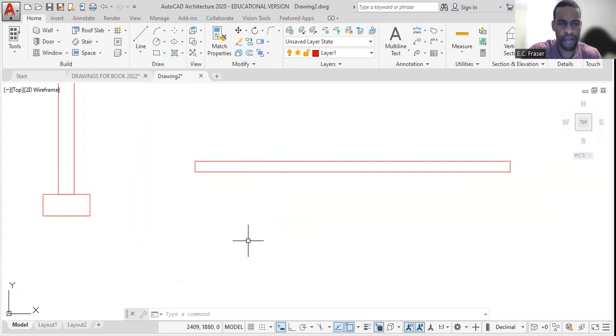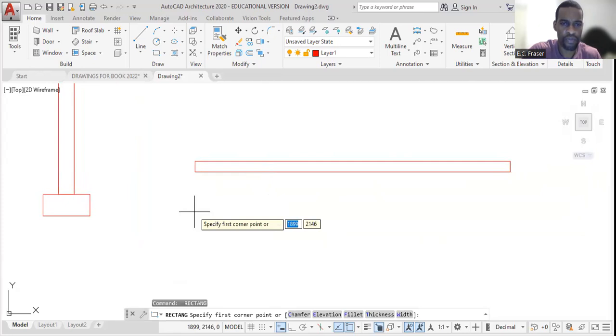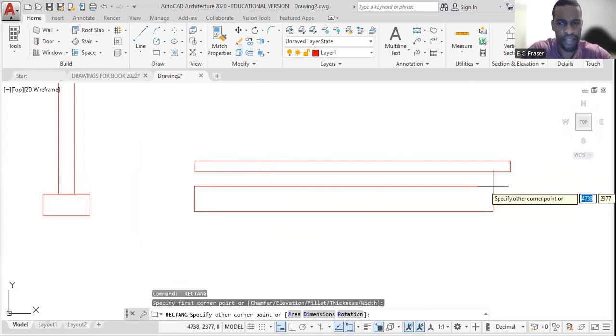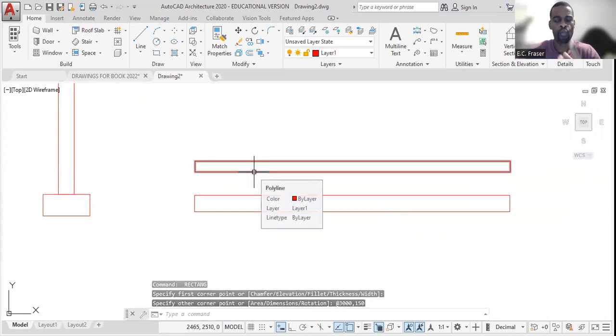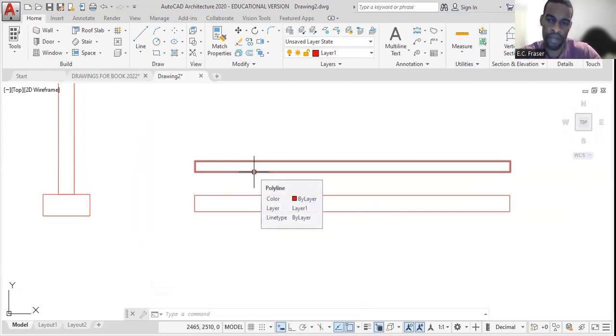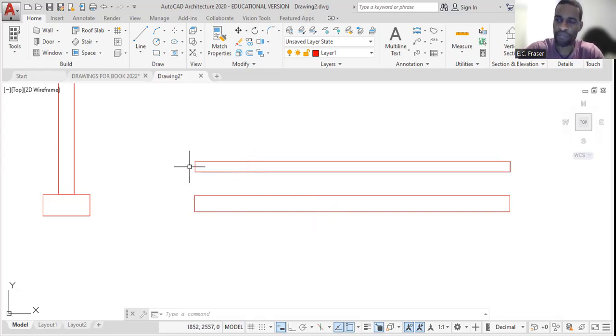Below the slab, we have the hardcore. So space bar, I left click here, shift @ sign 3000, comma 150, which is the standard thickness for the hardcore. You know what would have been good if I started from the low, from the earth, and worked my way up. That way I could pretty much put everything in place. Yeah, I probably could do that. Should do that. All right.